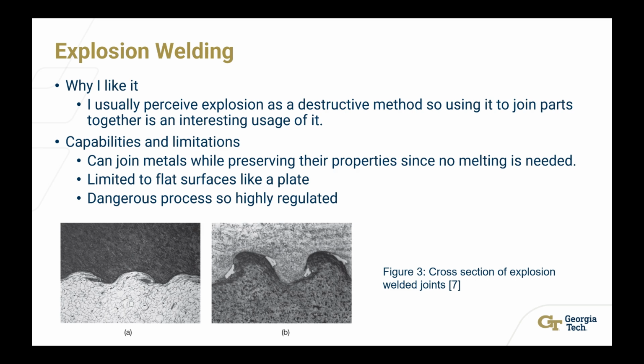For explosion welding, it can join two metals while preserving their properties since you don't use heat to join the materials. However, explosives are incredibly dangerous, so they're highly regulated, and they're also limited to flat surfaces to reduce the possibility of gaps when joining the material.